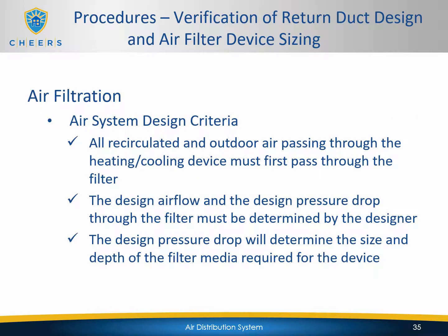So the design criteria basically means that all recirculated and outdoor air passing through the heating or cooling device must first pass through the filter. The design airflow and the design pressure drop through the filter must be determined by the designer. The design pressure drop will determine the size and depth of the filter media required for the device. So basically, you're just making sure that whatever is being installed matches what's on the plans and what was specified by the designer.